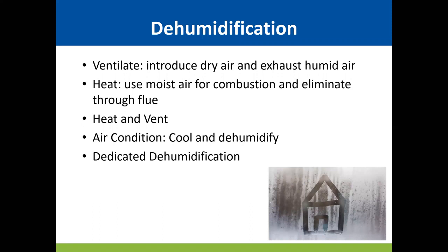We can heat. Now heating actually, if we just heat, let's say we just use hydronic heating with bench heating, then all we're doing is we're raising the temperature and lowering the relative humidity and vapor pressure deficit, but we're not actually removing any moisture. But if we do use the air from inside for combustion and eliminate those byproducts, including water vapor, to outside the greenhouse, or even the warehouse, then we can actually reduce the water vapor content of the air.